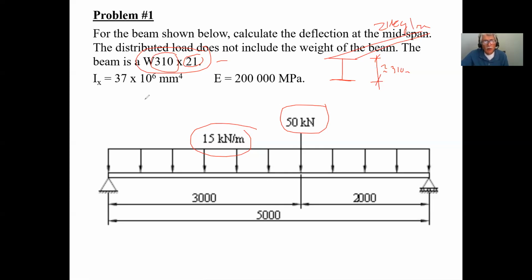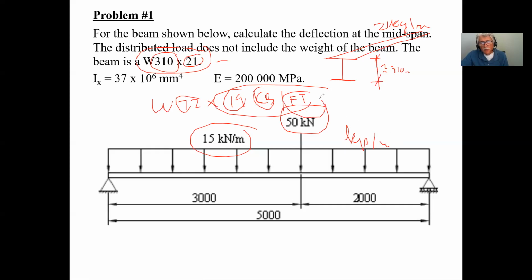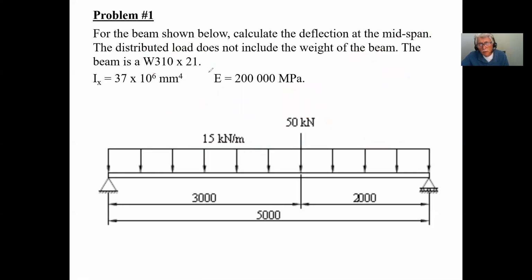If you happen to have a problem in imperial, you end up getting a W12, let's say a W12 by 19. Remember, this is 12 inches. 19 is already in pounds per foot. Therefore, you don't have to convert that into a force, but you do have to worry about that if you're working in kips. Okay, this is in pounds, and of course, if you're looking at kip-inch, this is kip per foot. So you have to worry about the units if you're doing something in imperial. Just to remind you, I think we did an example of an imperial one in the lecture.